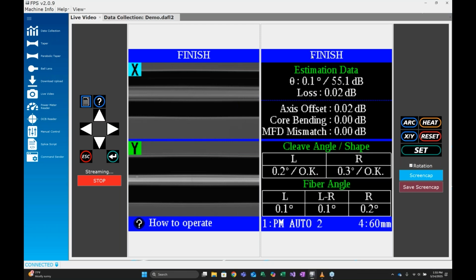If there's another object in the field of view, that can mess with the splicer. So the first thing I would say is maybe adjust the electrode gap and opt to use a special arc calibration instead of standard arc calibration. If you physically spread the electrode gap out, that will move the electrodes out of the field of view and keep that from being an issue.